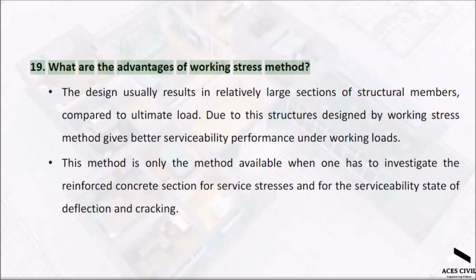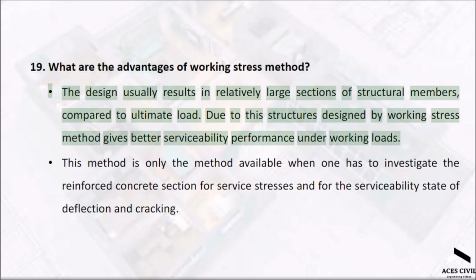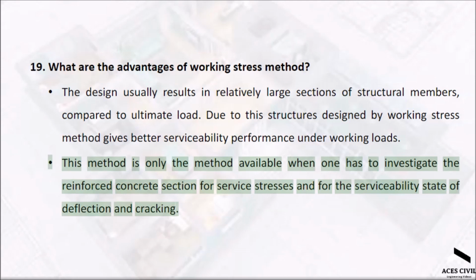What are the advantages of working stress method? The design usually results in relatively large sections of structural members, compared to ultimate load. Due to this, structures designed by working stress method give better serviceability performance under working loads. This method is the only method available when one has to investigate the reinforced concrete section for service stresses and for the serviceability state of deflection and cracking.